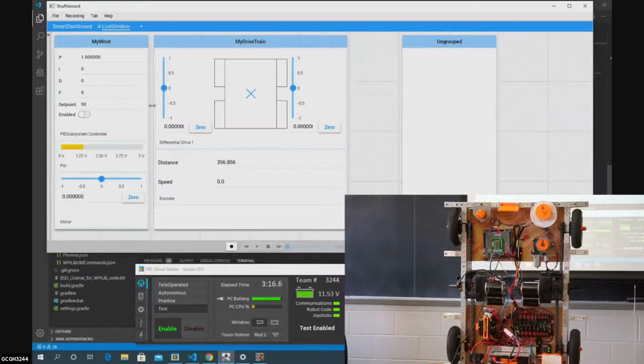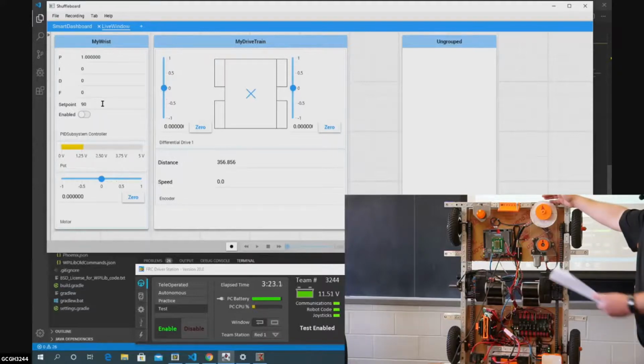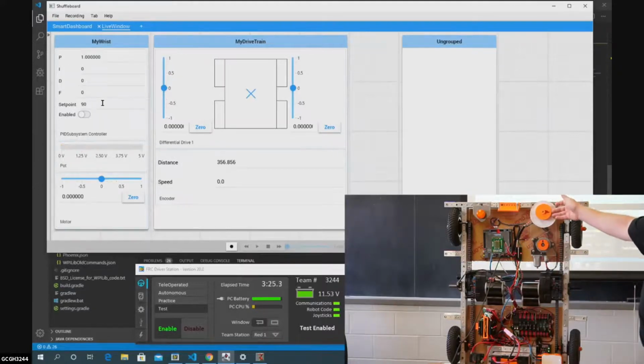When we set up our input device, we don't want to hit max to max. And then today, even though our output device, our arm, says it can go all the way back here, we're going to say that this is a hard stop. This mechanism can never go beyond straight up and down, as well as that is our down hard stop. So we're going to have a 90-degree range of motion. But what we want to do, instead of saying 90 is our 0 and 180 is our down, we're going to create some user units, and we're going to offset this.